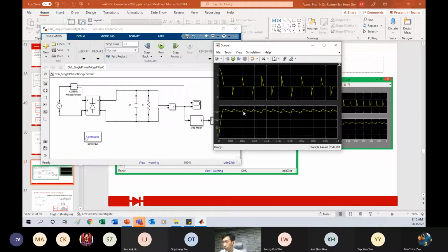When the capacitor is charging, it is basically just like a short circuit or a very low resistance, so it will draw a lot of current at once, and then slowly it decreases. This is a characteristic of the capacitor, and these are the currents that the grid side, the AC side, will see.